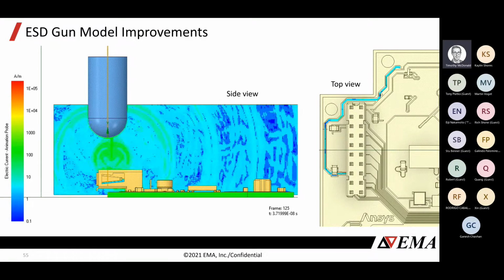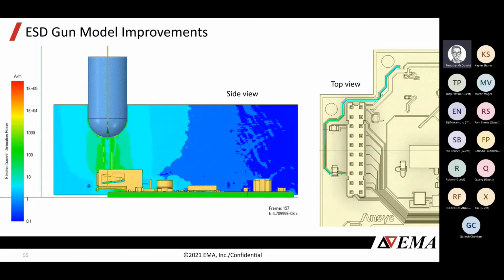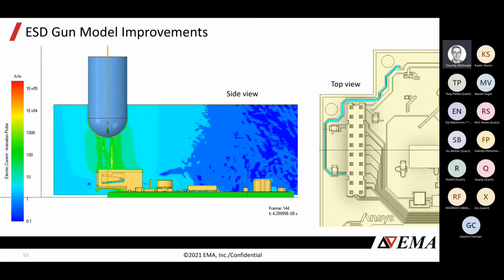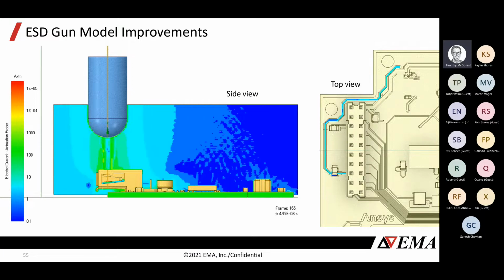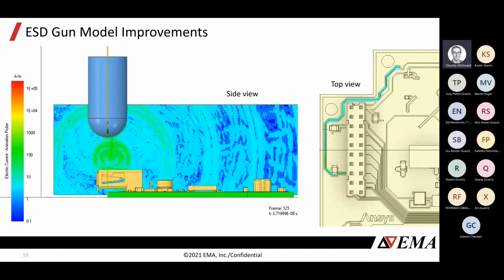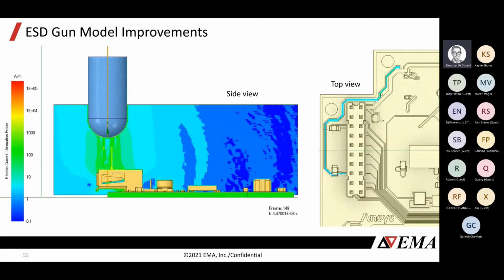We're going to keep ramping it up, and there it goes. We've got an arc. We're arcing to this USB housing. And now we can look on the right. You can see simultaneously we're inducing currents and voltages, but visualizing current right now on one of the traces of the Arduino board that's not necessarily in the direct path of conductivity. So we can see coupling from fields and waves. We can see direct coupling. You couldn't dream of modeling this in a pure circuit model, and certainly to capture all the physics, this would be hard without this tool.